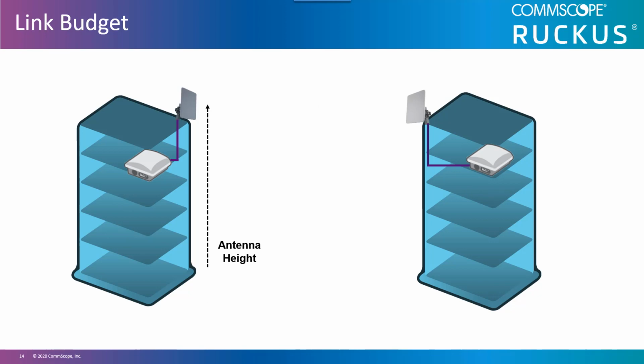Antenna height. This is based on the distance the signal needs to travel and the height of structures to which the antennas will be mounted. It's to overcome any blockage between the antennas. Line of RF sight, or the Fresnel zone, ensures the outdoor wireless point-to-point connections do not have any natural or man-made obstructions that would cause the link to have problems with stability.